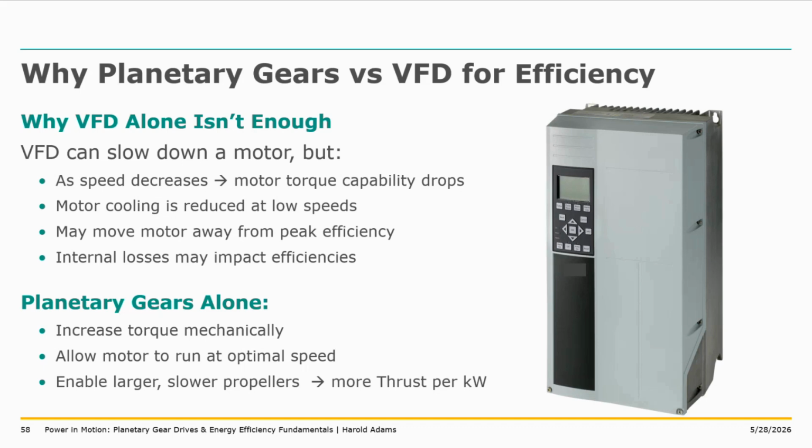On average, the VFD's efficiency is approximately 95 to 98%, meaning that after the losses in the equipment itself, we now have to internalize the losses with the VFD. Those losses are realized through several different means, through the switching, harmonics, and heat generation, and the cooling requirements, and an additional cabinet or control space that we would need to house this.